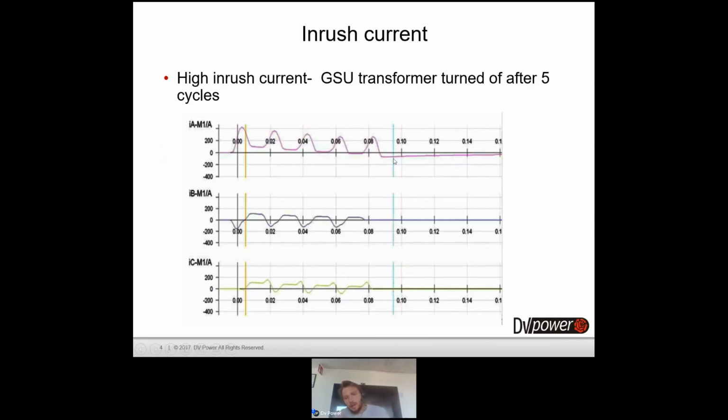So it was quite a long duration of inrush current. In this commissioning testing, there was a lot of issue with the conclusion of what was happening, because each time they started up the transformer, protection relays operated. So everything was fine with that transformer, it was just necessary to perform demagnetization.